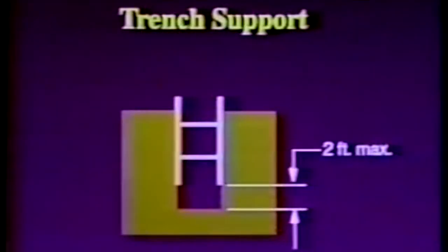Installation should begin at the top and progress to the bottom of the excavation. Removal reverses this process. Installation of support systems is to be closely coordinated with the excavation of trenches. Backfilling shall progress together with the removal of support systems. Material may be dug to a level no more than 2 feet below the bottom members of a support system